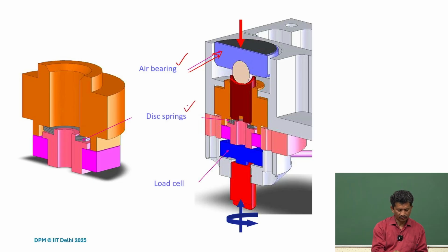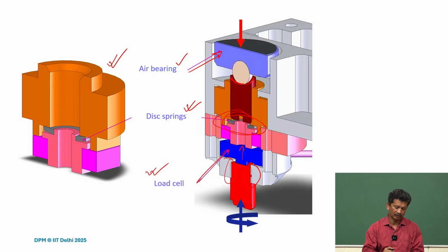You can see the disc springs here. So we designed this adapter module, which has a way to put the disc springs, and it can be adjusted. We have the load cell here for the measurement, and here you can see it is threaded. So if we turn it, we can press it. Then the disc spring deforms, and it applies that preloading to the bearing surface.